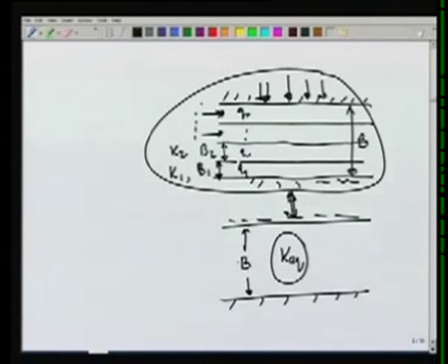In the case of flow being perpendicular to the layers, the discharge is the same through all the layers, Q, but the head loss in each layer will be different and has to be added to get the total head loss. So doing these computations, we can obtain the equivalent conductivity for this case.